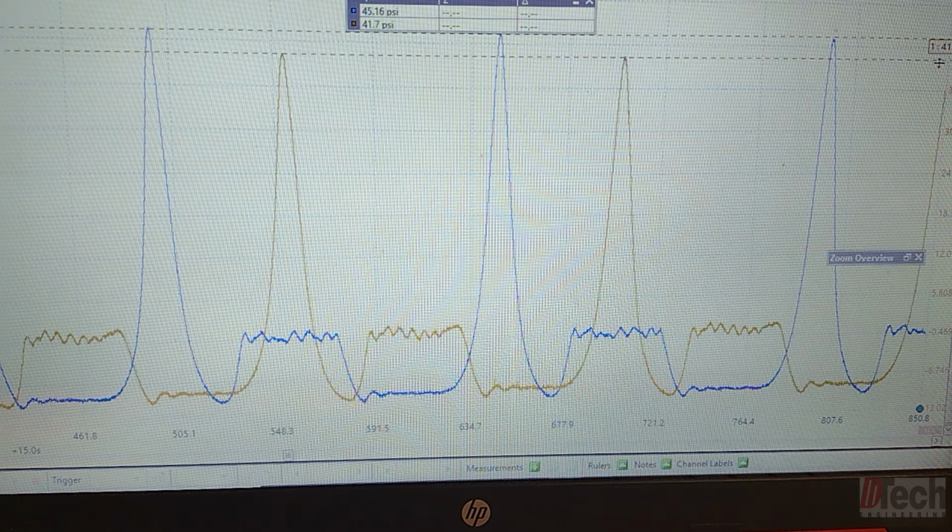can visually see it. Even down on the expansion pocket just before exhaust valve open, the difference is not even the level between the intake area from the expansion pocket. It's not offset, and it reaches about the same level. And again, if you didn't have cylinder 1 to compare it to, you almost wouldn't be able to tell or know that there was a mechanical issue. The way that we can is by comparing a known good and letting the idle stabilize.